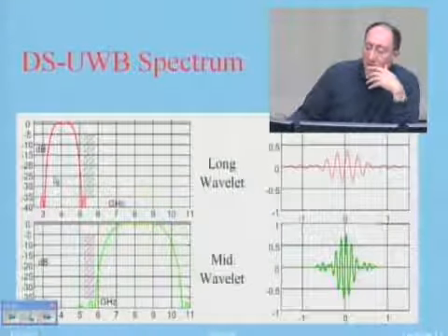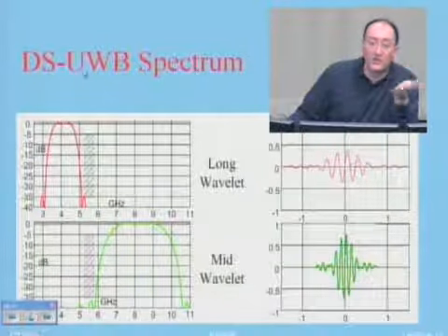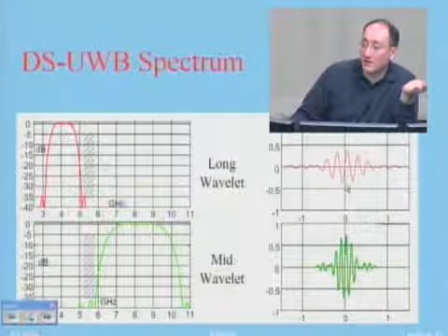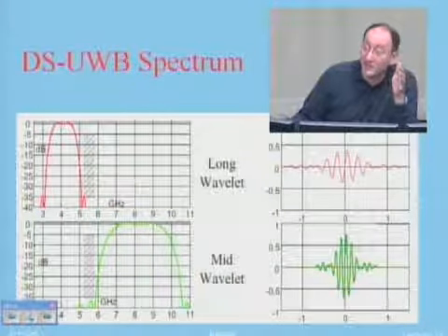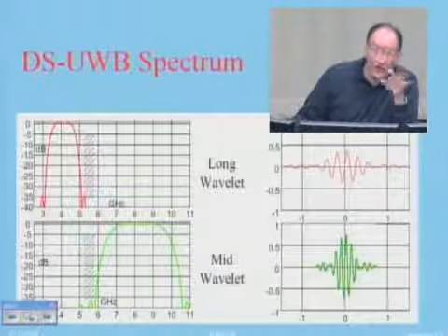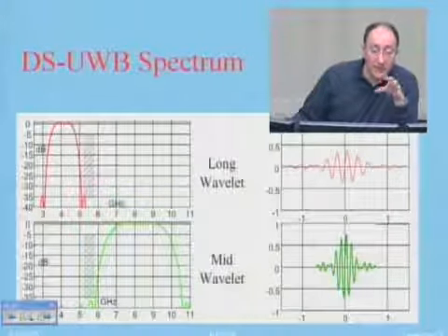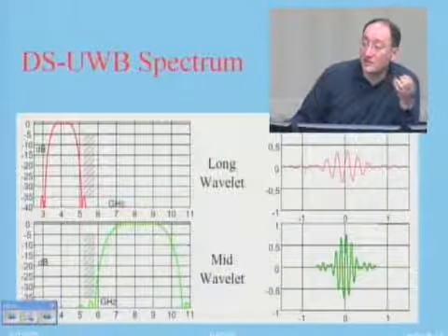And what they do is that they take these pulses and they do a spread spectrum with that, direct sequence spread spectrum with those pulses, like in-phase, quadrature phase. But this is baseband modulation, really. It's not RF modulation. Means that I'm not modulating it over anything. I just send the pulses.